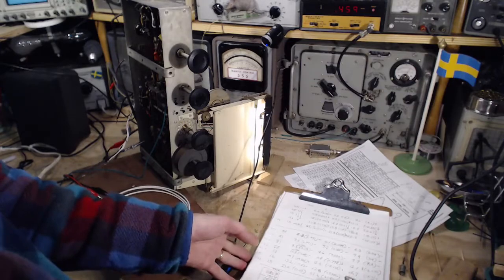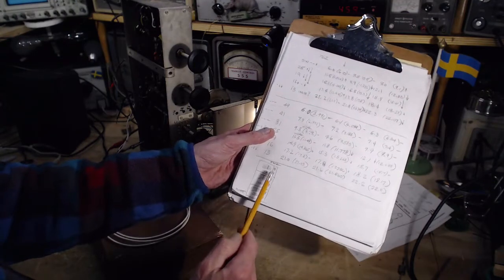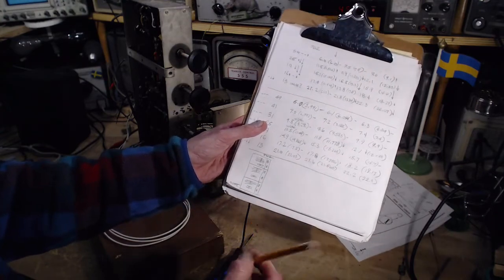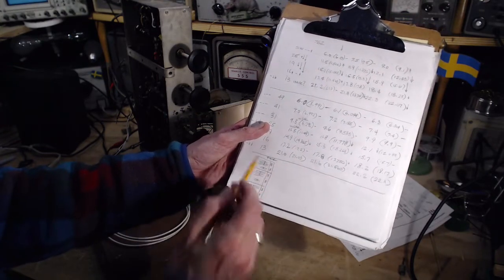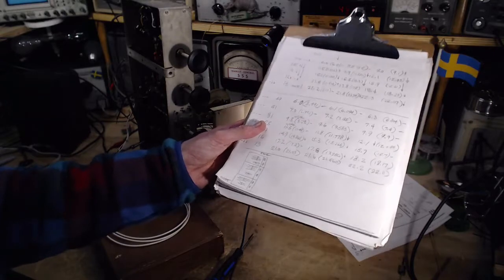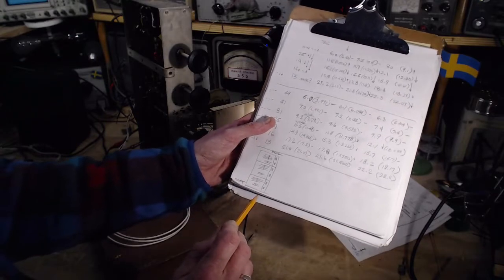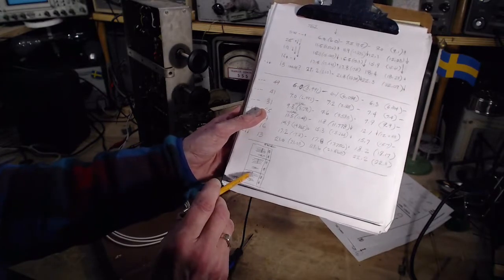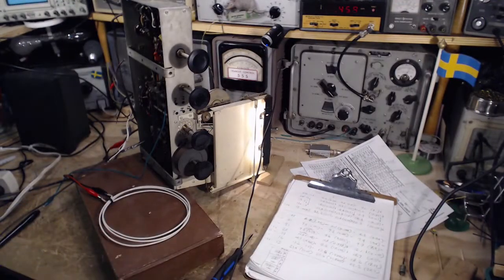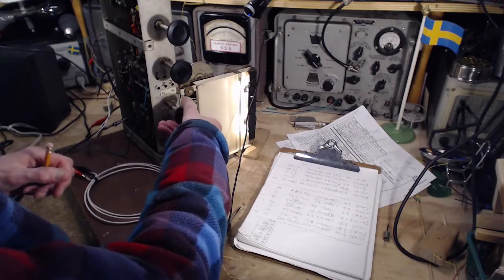Here's how I'm going to solve it. I've made a diagram of the tuning capacitor with its multiple plates and then a couple plates, and then all the trimmers, which I'm pretty sure just line up with what they're trimming. I'm going to investigate empirically what each of these is doing as I go through the bands, and try to identify which one is the oscillator control capacitor on each band. I'm pretty sure it's this one all the time. That's what it would be in an ordinary radio, but I'm not so sure this is all that ordinary anymore. It's become really weird. So we'll go on. This is a long process again.